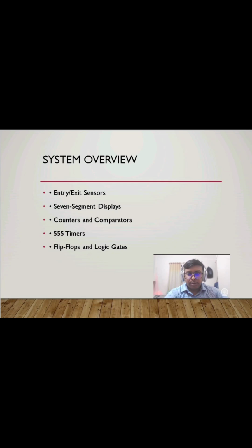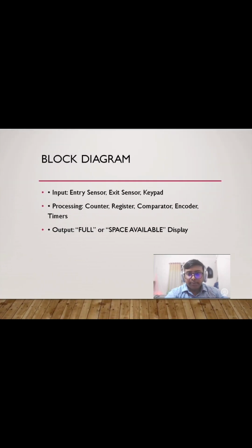And let's talk about the FSM. It ensures the correct timing, 4 milliseconds on and off for the display, and the state transitions happen on clock edges, while outputs are combinational. So in the block diagram, here is how the components interact.